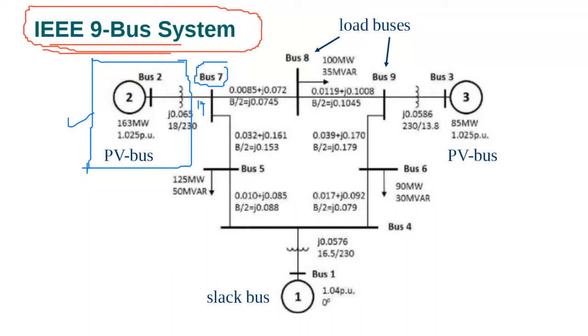Just outside there, a very big cable, and then you raise it up to 220 kV or 66 kV, so 10 times, 20 times or 30 times, because it is only 6.6 kV out of the generator.